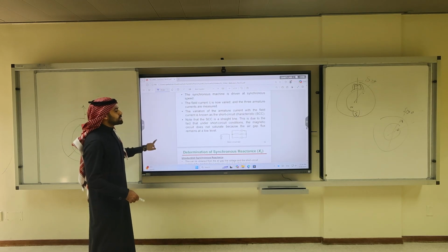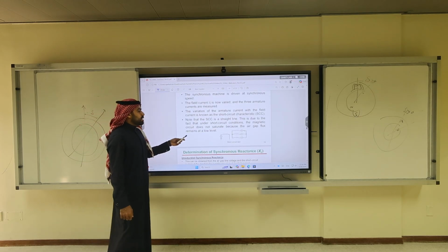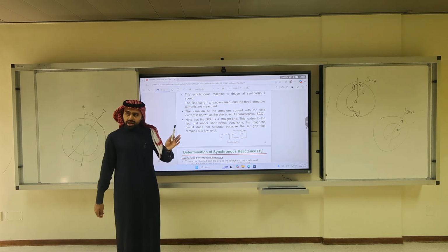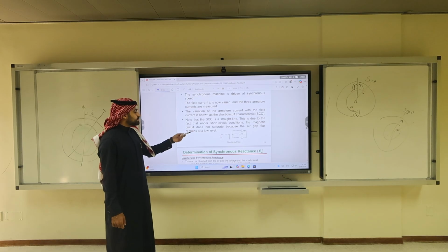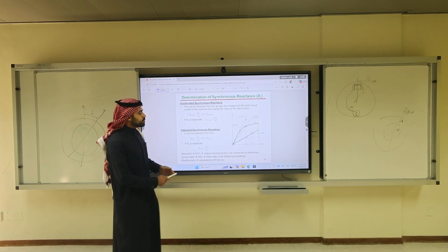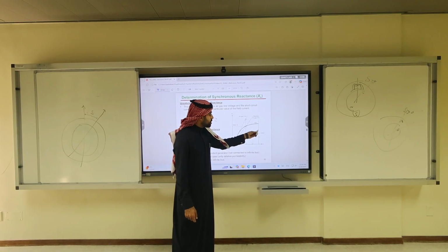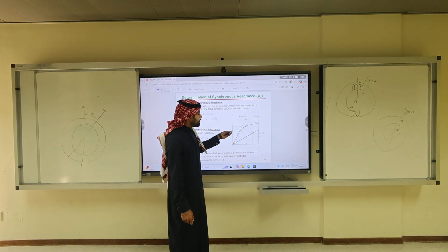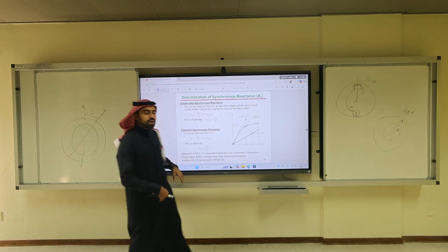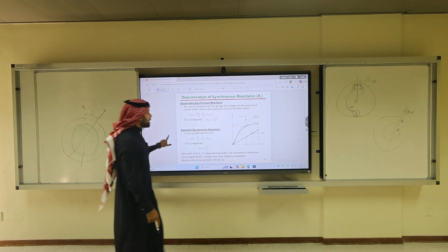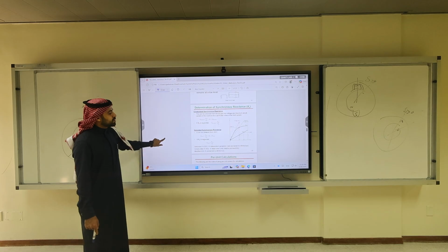Then what will happen is, for the short circuit, we don't need to worry about saturation, because even if you change the field excitation, even if you change IF, your EF is never reaching the saturation. It's here. This EF is low for a short circuit, so you don't need a modified line. You just use the SCC. And then you use the equation.